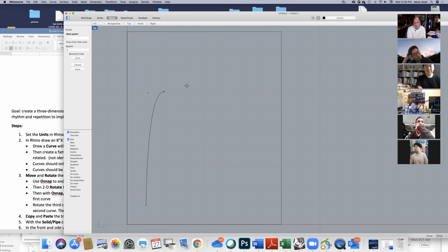Okay, so if I wanted sort of like a French curve, I would have these fairly close together at the top. Now, it wants to keep drawing. It wants me to keep drawing a 4th point, but I want to stop at 3. So it is right click.